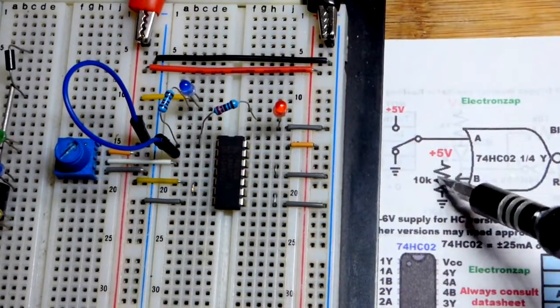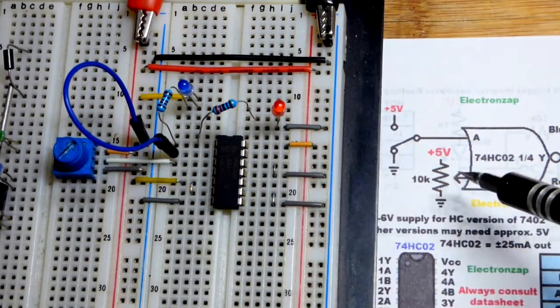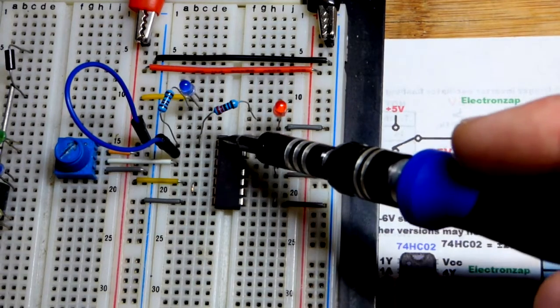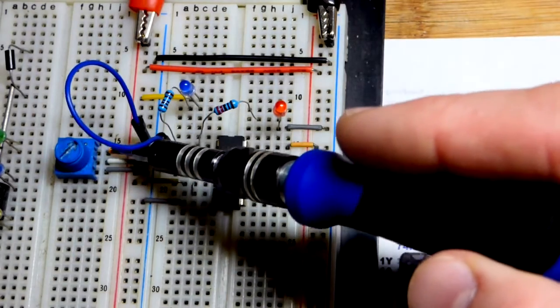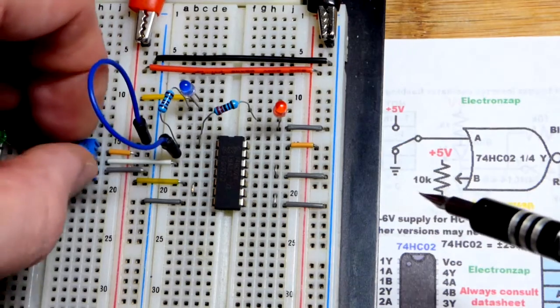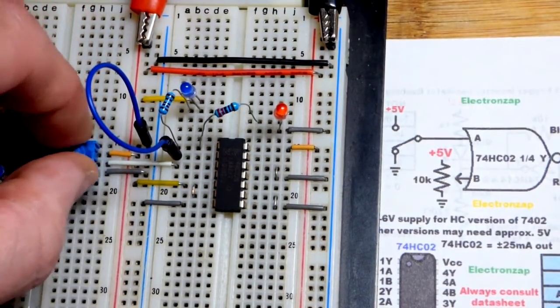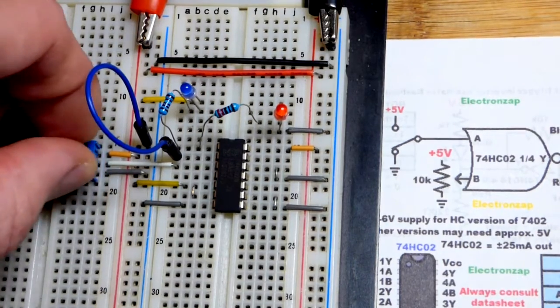The inputs, pretty straightforward. We got a trim pot right there. The middle pin is the wiper, so that slides across the resistive element. It's going to B, so it's output Y, and then A, and then B right there. The other two ends of the resistive element are connected to the positive supply. So up there is high, close to 5 volts, and then when we get a little more than halfway to ground, it'll go low, down to 0 volts right there.